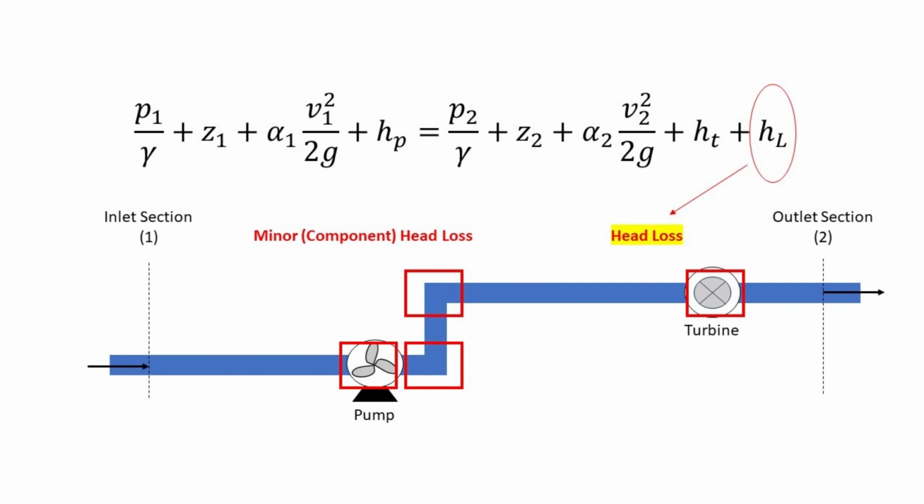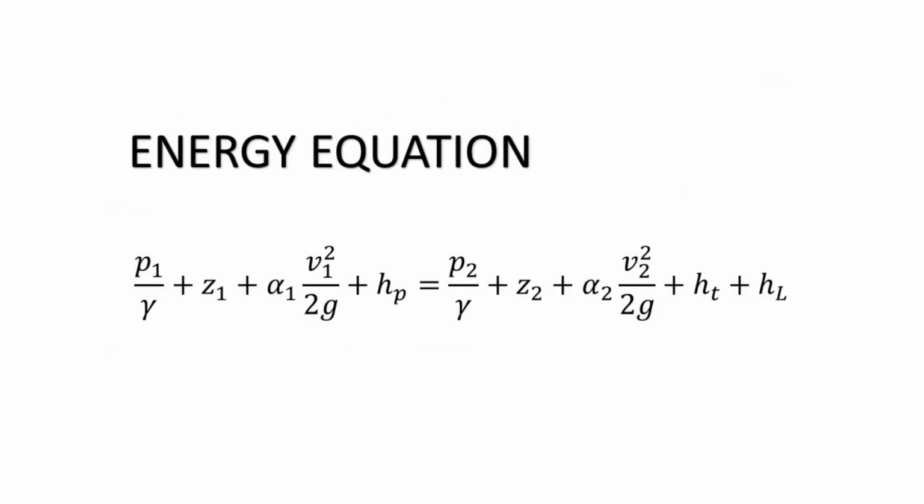For relatively short pipe systems, with a relatively large number of bends and fittings, minor losses can easily exceed major losses, especially with a partially closed valve that can cause a greater pressure loss than a long pipe. When a valve is closed or nearly closed, the minor loss is infinite. Head loss holds significant importance in fluid mechanics, and this topic will be covered extensively across multiple sessions and separate videos.